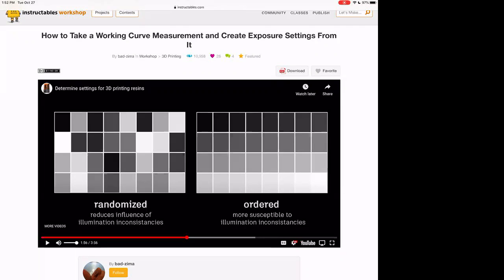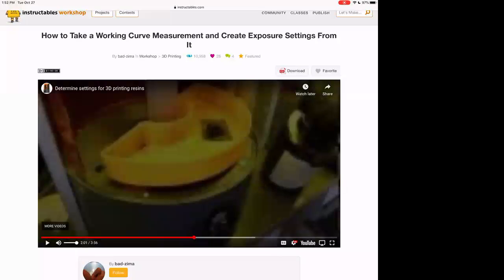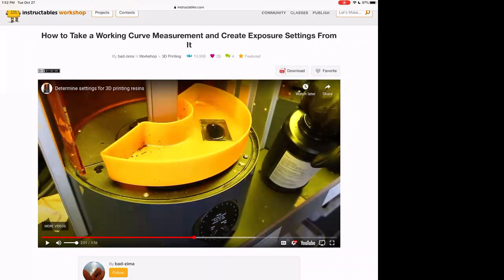And so when we're looking at pictures like this, it represents how the light is coming up through this gray area right here, which is the PDMS window. And of course, the light source in the Ember is coming from the bottom where that gray cylinder is, where the little screen readout is. So this is a bottom-up DLP illumination. So the Ember is not a raster scanner, it's a full DLP setup.